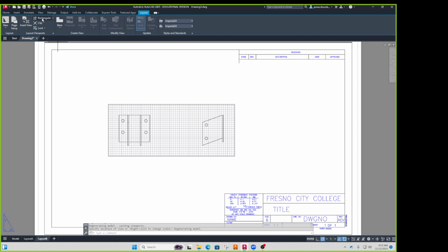If you make the rectangular one, it's going to show you everything. So if I have a lot of things in model space and I want to pick out certain areas of it, rectangular kind of makes it a little cumbersome because I have to look at everything and zoom in on where it is. Whereas insert lets me do that all at once. But if I only have one thing, I usually go with rectangular. If I have to come up with a logic of why I use which ones, if I have one thing in model space, I'll usually just do rectangular. If I have a lot of things, then I'll do the insert view.